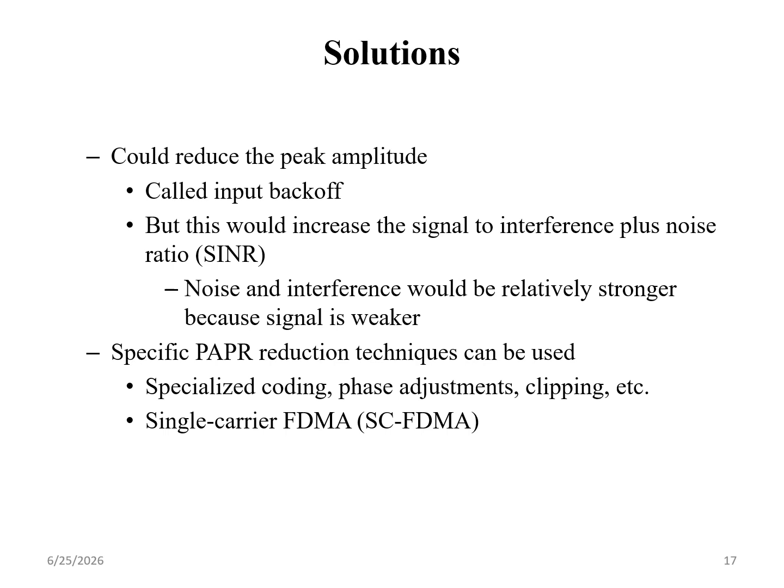That was the concept. A specific PAPR reduction technique can be used: specialized coding, or you can adjust the phase, or you can go for clipping, or in other terms, you can use SC-FDMA, single carrier frequency division multiple access technique. So to reduce it, you can use coding, phase adjustment, clipping, clamping, or SC-FDMA.